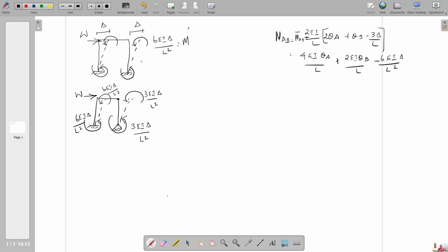So you have to note this point that when the fixed support is given, the moment created due to the horizontal drift or delta deflection is 6EI delta by L square, and anti-clockwise in nature. And for the simply supported case, it is 3EI delta by L square. Because we are going to deal with this term, hence we have to understand it.